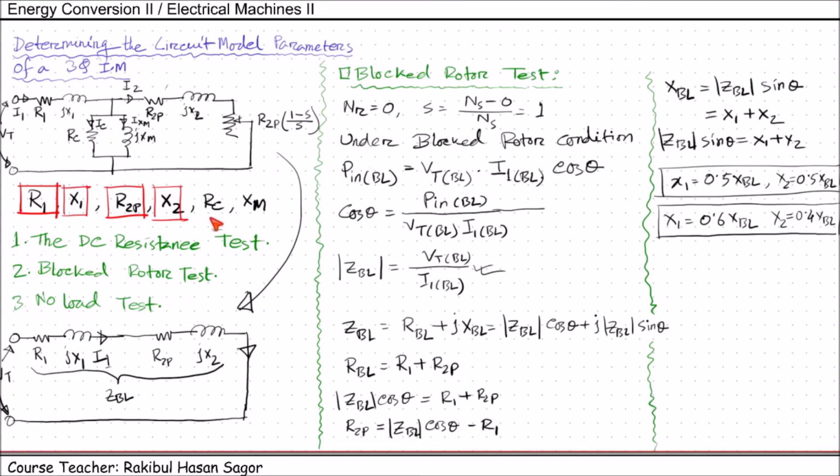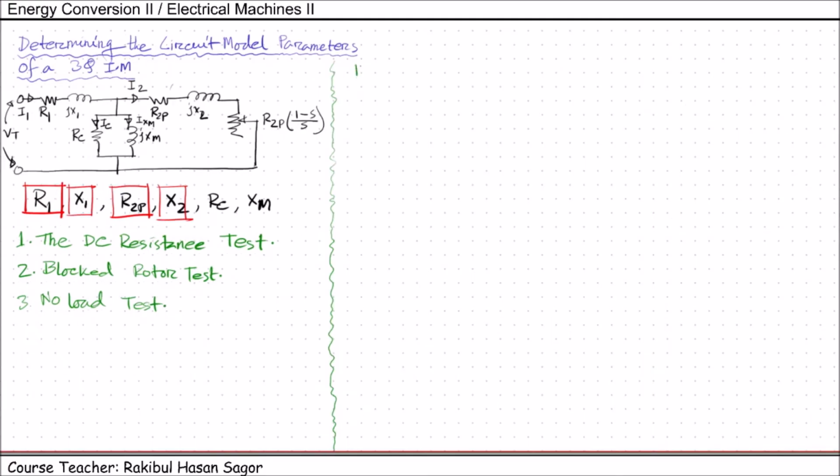Still we need to know the values of R_C and X_M. In order to get those values, we need to go for another test, that is the no load test. So we'll start the no load test for the 3-phase induction motor.